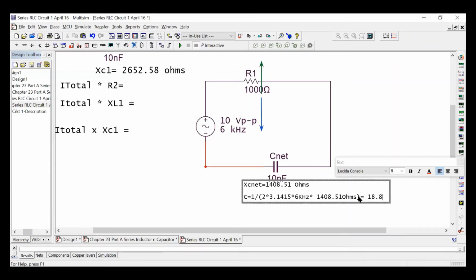It's like 19 nano. Yeah, you can go 19 if you rounded up that 18. You have 1.8 e to the minus 8. It actually comes out to be about 18.83 nanofarads. A really small capacitor. You know, this circuit reminds me more of a communication circuit with the capacitor so small. So, yeah. Did I lose anybody on that?